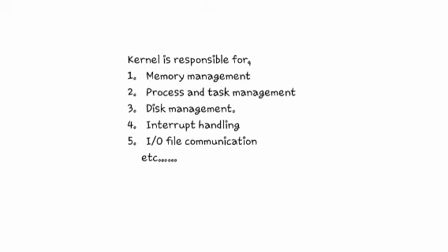It enables process creation, activation, running, blocking, resumption, deactivation, and deletion, and it maintains the process structure in a PCB. Process scheduling, for example, cyclic scheduling or priority scheduling. And inter-process communication, that is, the communication between tasks, ISR, operating system functions, and processes.